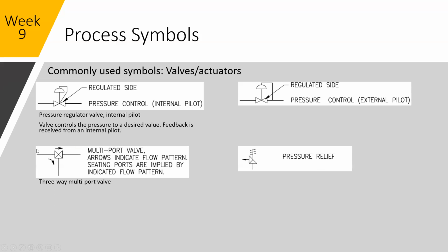If we had an arrow coming here and an arrow coming here, indicating that they both go this way, then this would be acting as a 2 input, 1 output mixing valve. Does that make sense? So this valve is able to send fluids in 2 directions or receive fluids from 2 sources, all depending on indications in the drawings to interpret the flow, the path of the fluid.